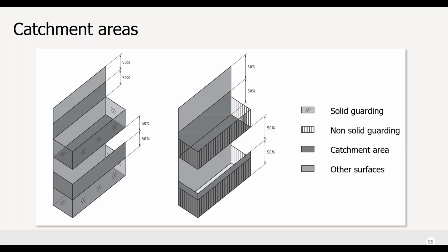Rainfall outlet design with an adequate width of the waterproofing flange is detailed in BS EN 1253. Of course, it's key to make sure that the waterproofing layer, and we've discovered that it could be in two places: it can be on top, on the walking surface, or it can be beneath.